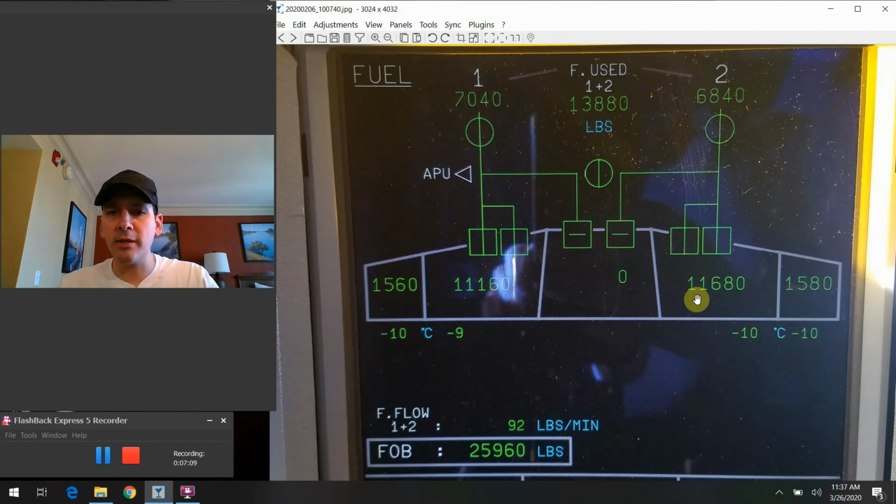And one thing to tell you a little bit also about the general fuel feed plan on the A320 is that anytime we have fuel in the center tank, the airplane always wants to extract the fuel out of the center tank first. So it'll burn all that out of there initially, and then when the center tank is depleted, it'll burn both the wing tanks down.